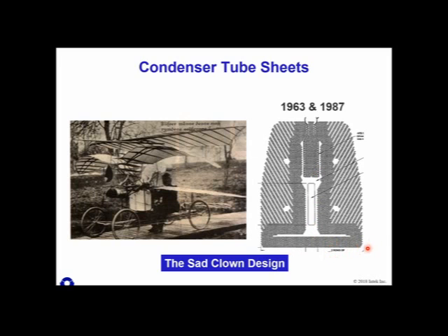This particular condenser had, the reason I have it here is it had a condensate tray underneath it and was marketed as a de-aerating condenser because of this tray down here. It caught all the condensate, allowed steam to scrub that condensate to warm it up, drive off the dissolved gases that were coming out of this bundle design.